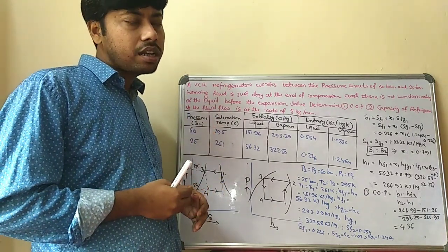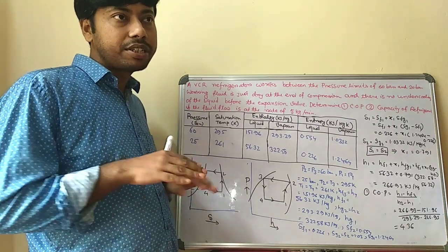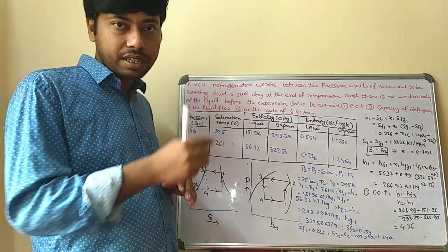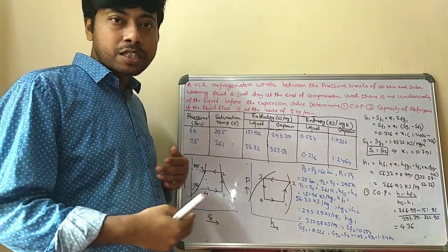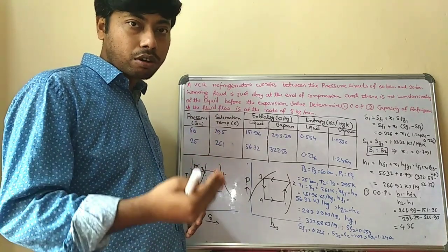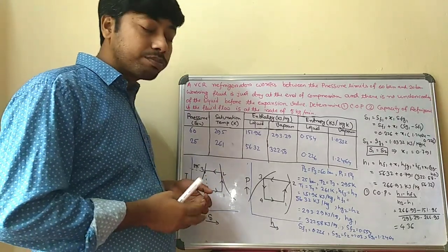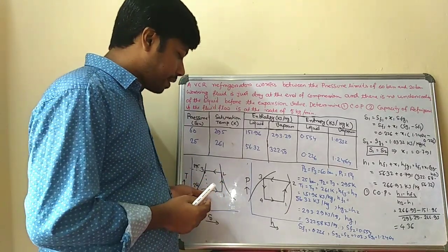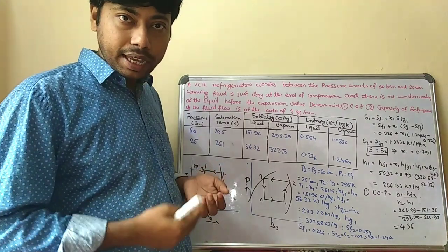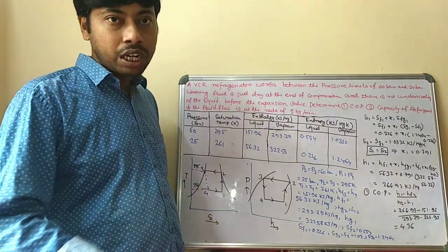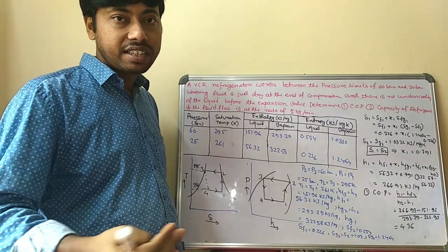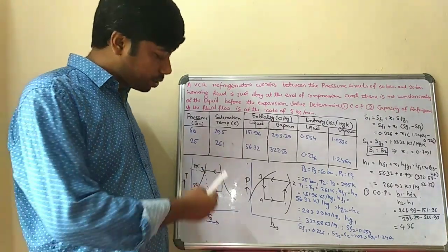After all, if the pressure limit is very high, you have to reduce the pressure from P2 to P1 by means of an expansion valve, capillary tube or throttling device. It is used in process 3 to 4, and in 4 to 1 there is an evaporator. If you plot these in a thermodynamic plane, meaning PV, TS, HS and PS diagrams, it will look like this.